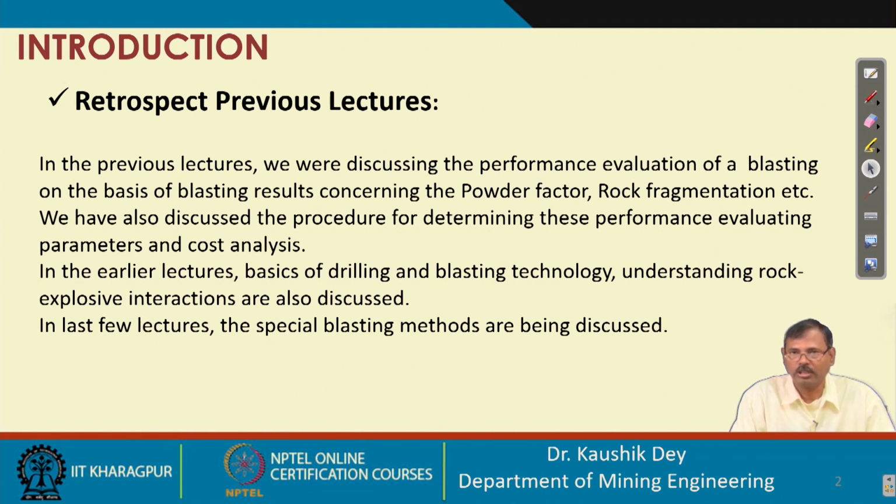We know the key performance indicators of a blast and drill parameters, how to identify those parameters, and how to calculate the cost analysis for drilling and blasting operations. We have also understood the impact of rock and rock mass properties on blasting performance. And currently, we are discussing the special blasting techniques.